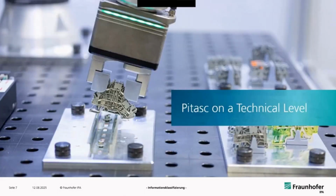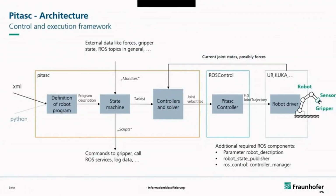Let me introduce Pitasc now on a technical level. As I said before, Pitasc builds upon ROS control and the robot driver itself. Robot programs can be defined as XML code or with a Python interface. The program then gets transferred to a state machine which runs the robot program and controllers.